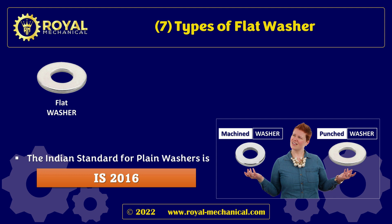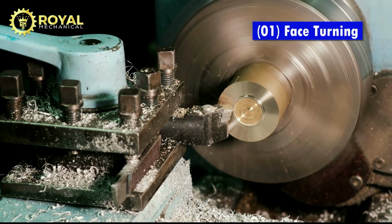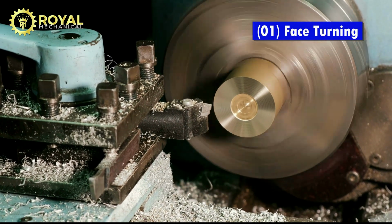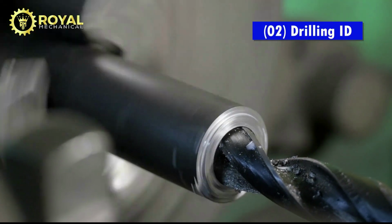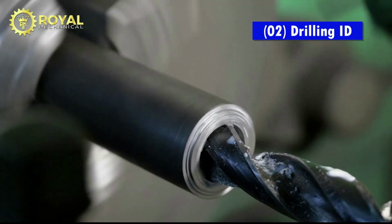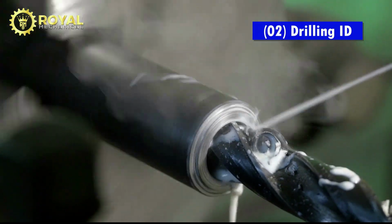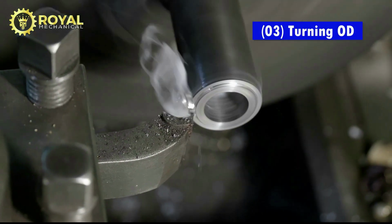Let's take a look at the manufacturing process of the machined washer. First, face turn the raw material. Then drill the inner diameter of the washer. Then turn the outer diameter of the washer.